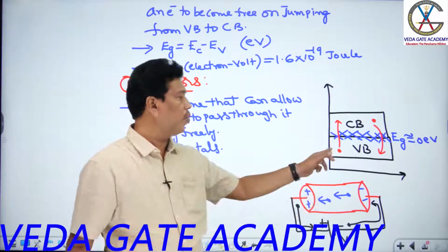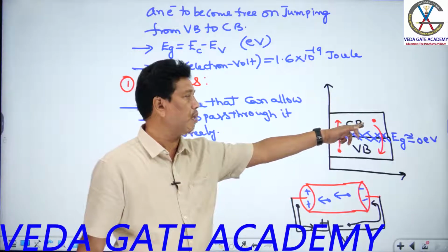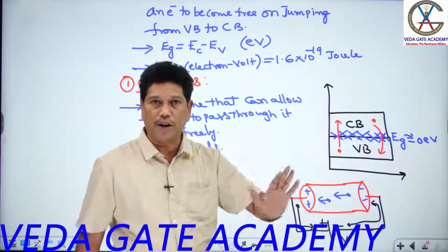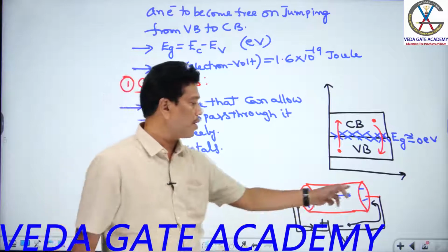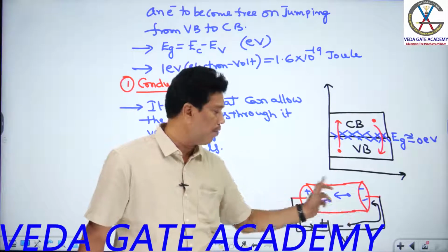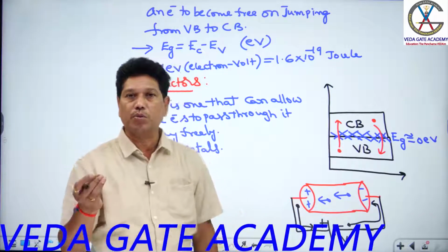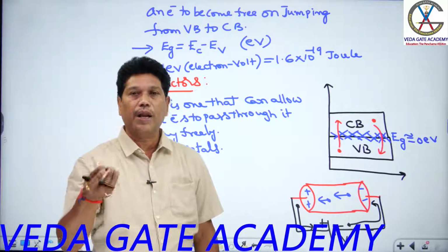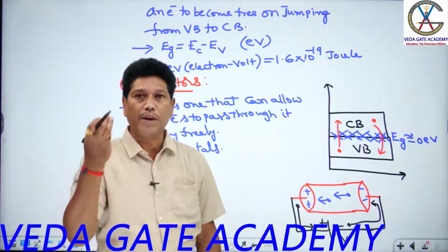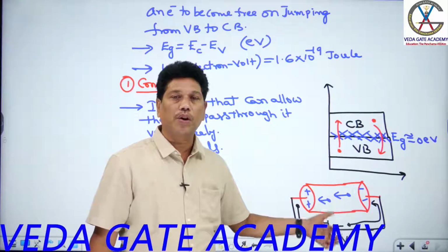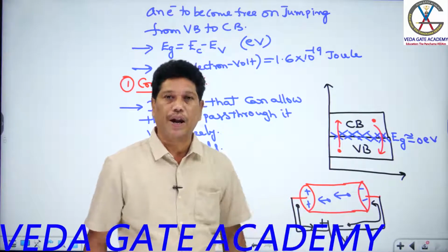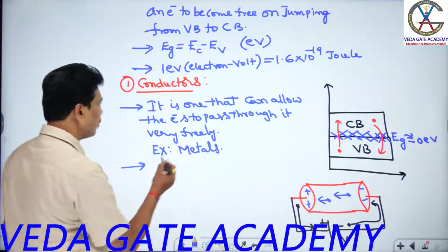Already I told you. Why, sir? Even the electrons go to the conduction band, so you don't say any loss of electron here. Confirm now? So current carriers are electrons only. What is the mechanism, students, drift or diffusion? Drift mechanism. Drift mechanism means making the carriers move in a single direction with an average velocity called drift velocity. Right? And due to their motion, you can generate a current called the drift current. See this now.